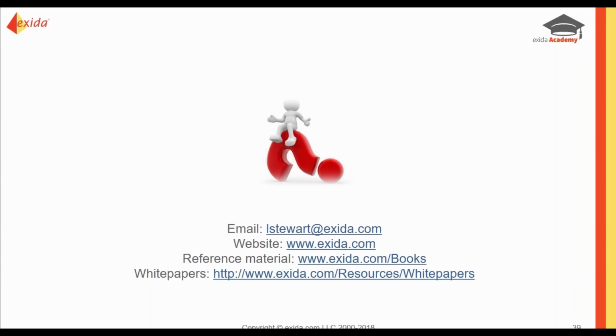The next question, how could you select a systematic capability for the composite? That is a great question. What I would do is take a look at everything you're comparing for your composites and see if they are all certified. If they're all certified devices, that's easy. You just take, once again, your weakest link or your lowest one and use that as the conservative approach. If they are not all certified devices, that could be different. That might answer if you want to be using them in your SIF. You can always do a different proven in use approach, but that's going to take a lot more time and constraint on you yourself as an end user.